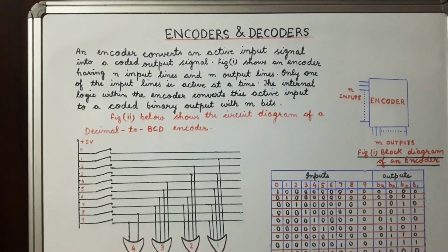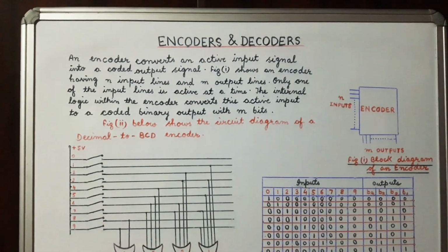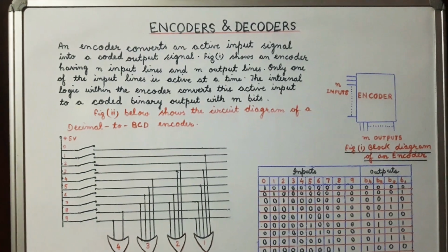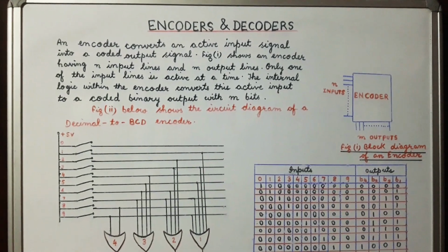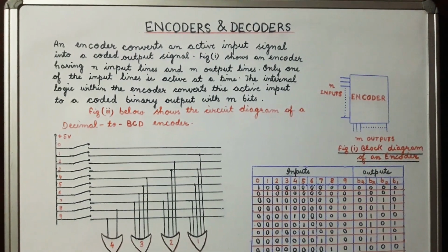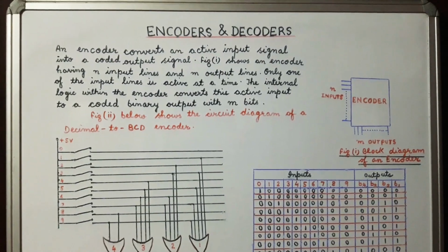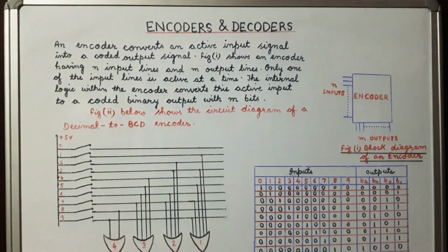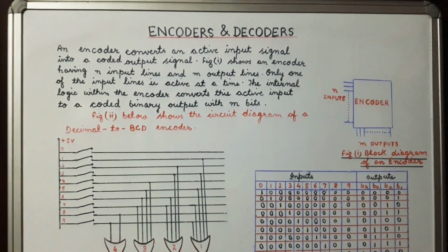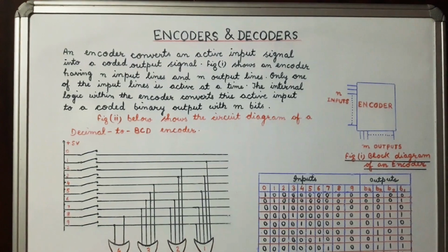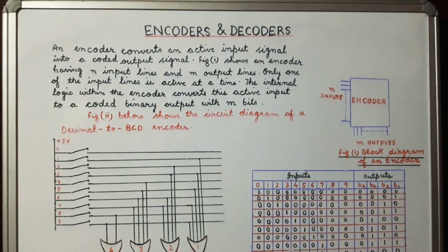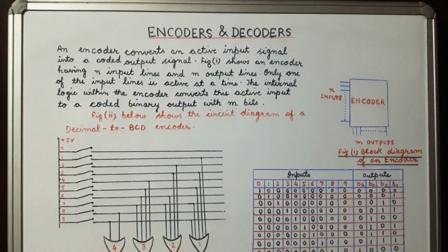One of the most commonly used input devices for a digital system is a set of 10 switches, one for each numeral. These switches generate 1 or 0 logic levels in response to turning them on or off. When we feed a particular number to the digital circuit in BCD, then the switch corresponding to that number is pressed. There is an IC which is available in the encoder to perform this function.